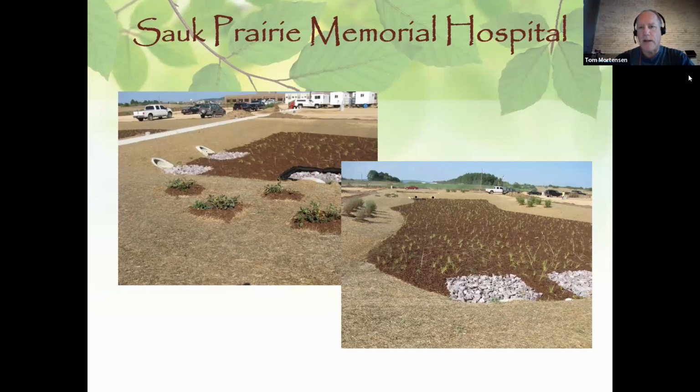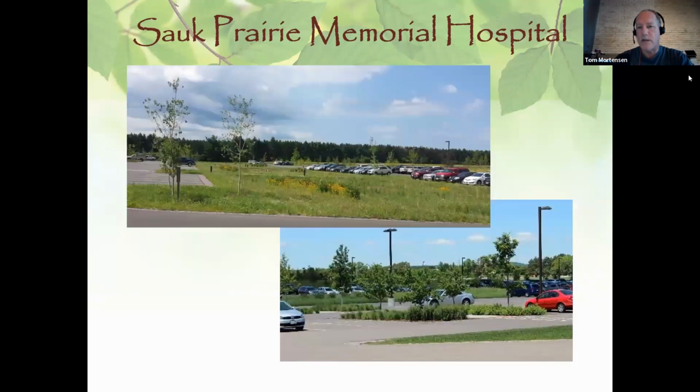They're not all just rectangles like I showed on the example, but we planted the side slopes with some native woody vegetation. This was planted with plugs, and I'll tell you the reason why this was so successful is because in our specifications, we tied the landscape contractor who was to install this landscape to a 3-year maintenance program that had to be implemented by a firm that had proven experience to take care of native landscape, because the landscape contractor did not have that on staff or in-house. So they had to bring in a specialty firm to take care of this native vegetation and these bioswales.